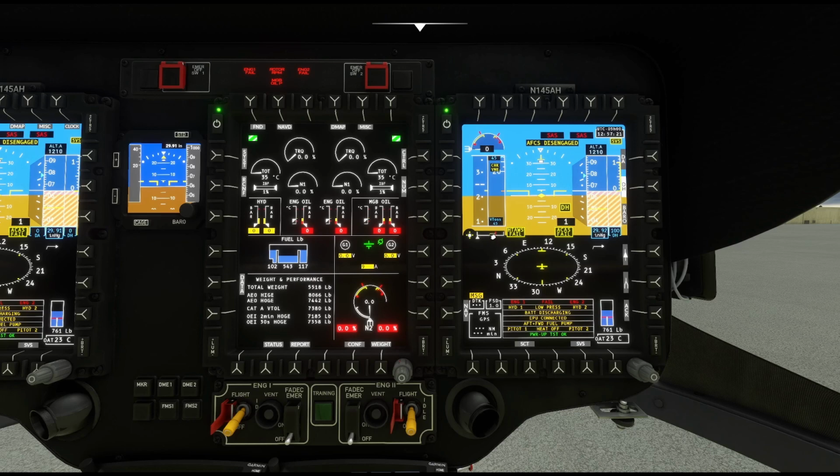So this is a transient zone right inside of here that when you get into this zone, you have to keep track of how much bending has occurred. And you have to keep track of it on the mast log card and each of the blades and transmit. There's all kinds of stuff that you have to enter in, and then certain components have to be inspected after a certain amount of mast moment, and even at a certain point are retired from service after they have experienced a certain amount of mast moment.